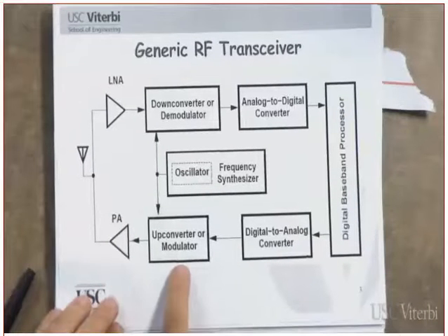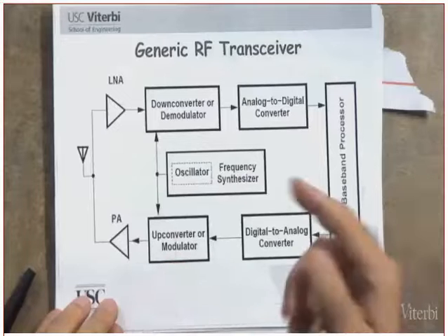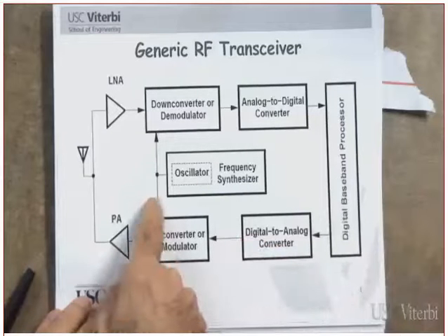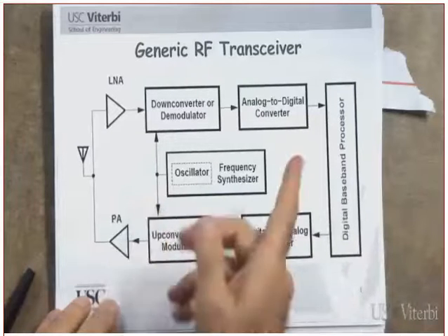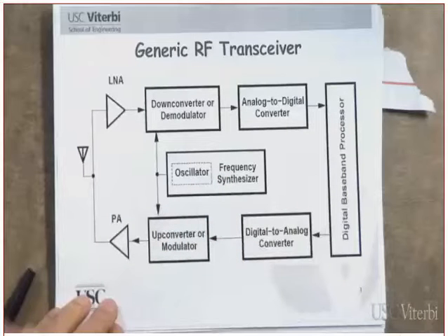Now, this one here, how many inputs does the modulator have? It has 2 inputs. One is the baseband, the other one is the carrier. Clear? From a local oscillator. This is a frequency synthesizer, the oscillator here. So it's a variable, voltage controlled oscillator.